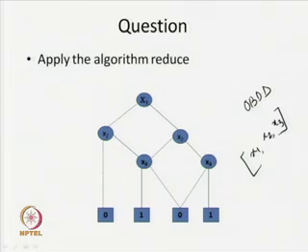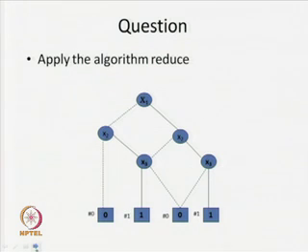So, in this particular case, what will happen? First, I am going to label these nodes. All 0 nodes will be labeled with 0 and all 1 nodes will be labeled with 1. Now, we have labeled the terminal nodes, then we go up. When I come to the level x3, 1 node is going to 1 and 0 node is going to 0. That means the sub BDDs are not the same. So, we are going to have a new label 2, and similarly, this is also at x3, 0 is going to 0 and 1 is going to 1.